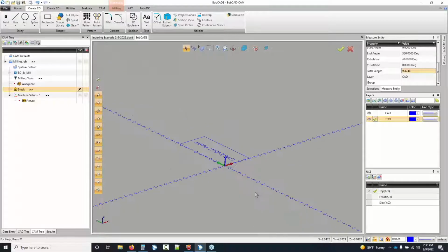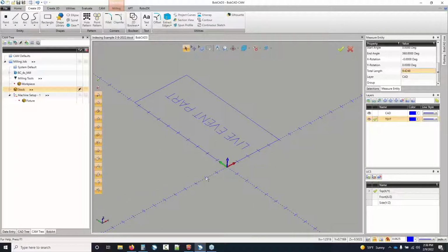All right, now, there's two other big things that we have to do. The first is get the geometry in the right place. The second is set up the wrapping group. So when I say we need to get the geometry in the right place, our geometry has to sit at the height of the radius of our part, because our origin is in the center of the part, right down the middle of the part. So my stock is 3 inches. I know that because I made it. It's easy. I just need to lift this whole thing up 1.5 inches.